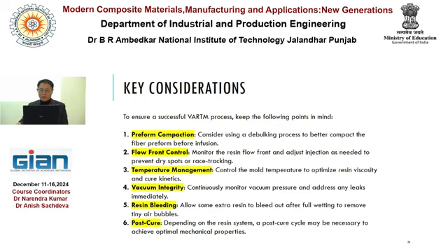preform compaction means that for the preform you have a stack of carbon fiber, for example. It needs to be preformed. But if you use too strong a compaction pressure, that means the preform will get pre-damaged. It is not wanted, right? So, for example, if you give too much compression, then local buckling can be found.